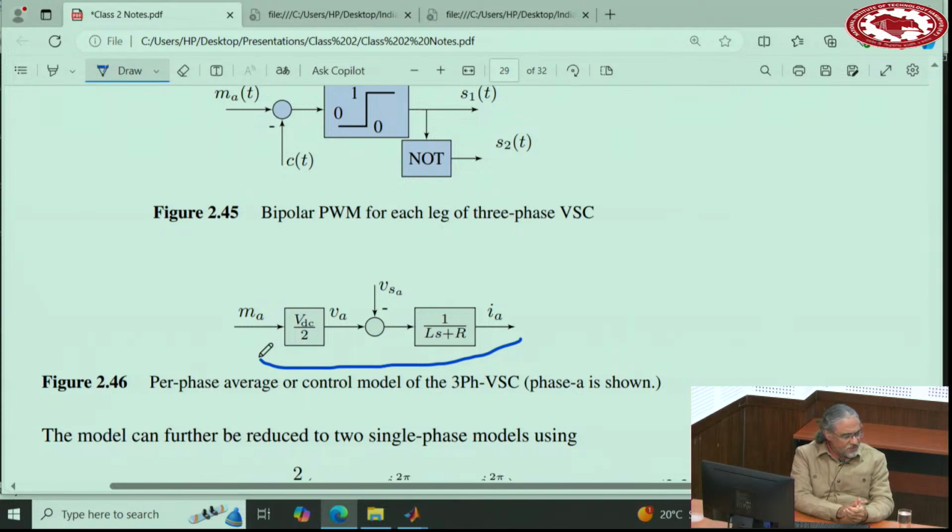However, under these assumptions that we made, VA plus VB plus VC equals 0, we do not practically have three independent circuits. We only have two independent circuits. So for that reason, it's not necessary to work with three. We can work with two. And that's the concept of a stationary domain or alpha beta domain. So the alpha beta domain converts ABC to alpha and beta. And it says, I don't need all three A and B and C. Let me only derive two, alpha and beta.